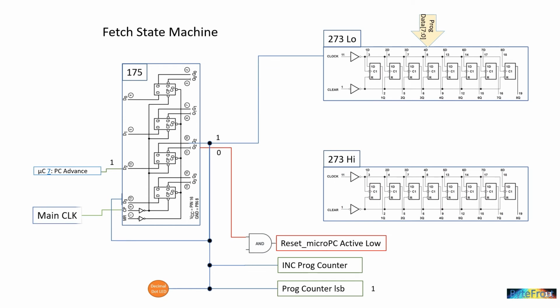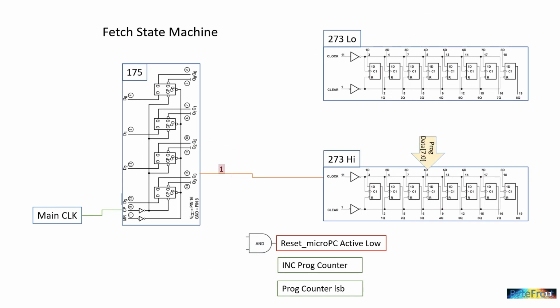Immediately after the rising edge of the clock, flip-flop 3 will output a 1 signal and cause the high instruction register to store the high byte of the current instruction, while at roughly the same time, the program counter will increment. There is an apparent race condition. The high instruction register needs to store the high byte of the current instruction before the program EEPROM's data output changes as a result of the program counter value incrementing. However, it will take much more time for the program EEPROM's data output value to change, so the high instruction register will never lose the race.